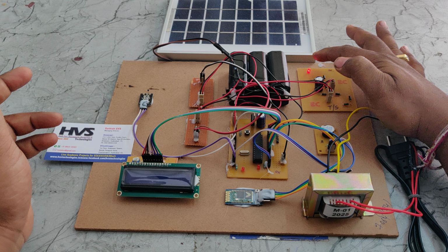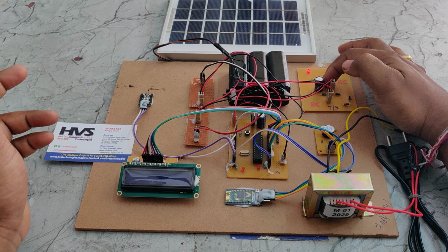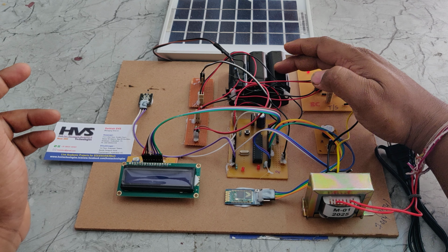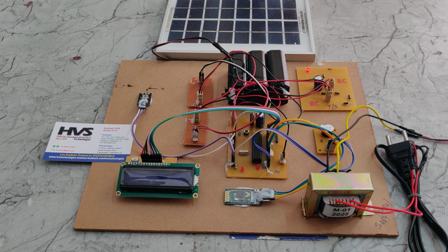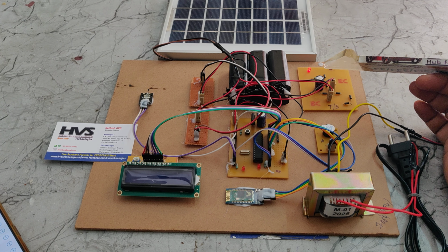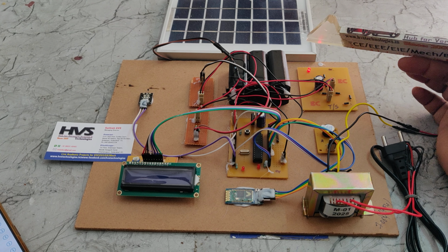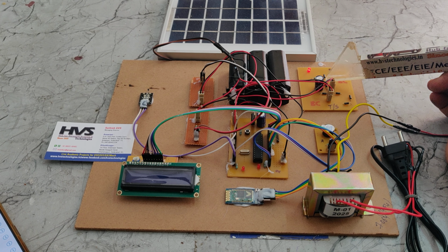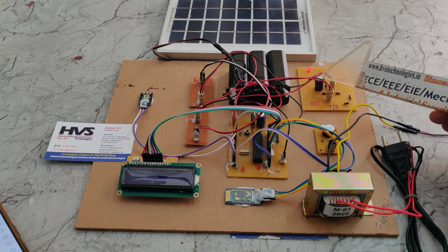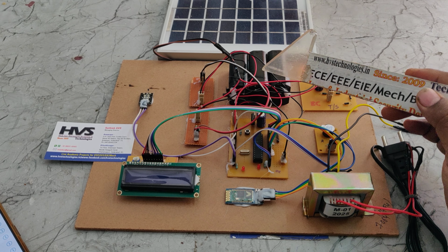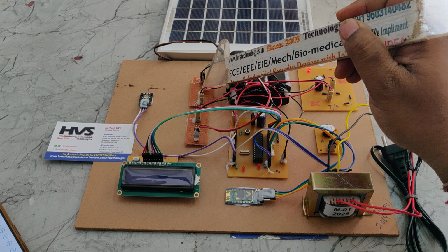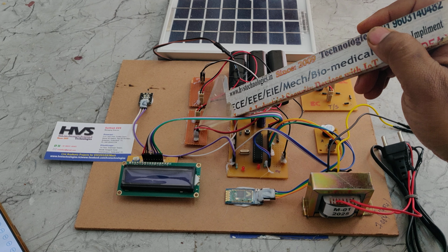The output is then fed to the LED, and through these 2 diodes we provide it directly to the 12 volt 1 amp battery pack. These 2 diodes block the current flow from the battery to the solar panel whenever it is fully charged, so they act for unidirectional current flow. The output from the charging circuit is input to the battery pack, and in parallel we measure the battery pack voltage with this voltage sensor and the solar panel voltage with this voltage sensor.